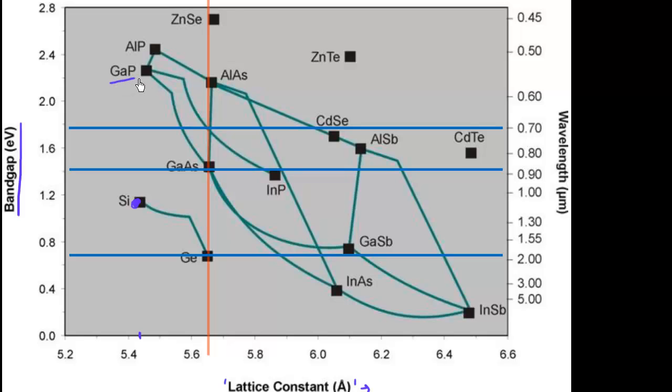The lone star over here is gallium phosphide, which has a lattice constant similar to silicon. So it's very hard to find 3 materials with different band gaps which can give me this optimum material set for a 3-junction solar cell based on silicon.